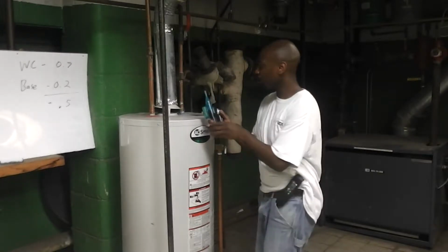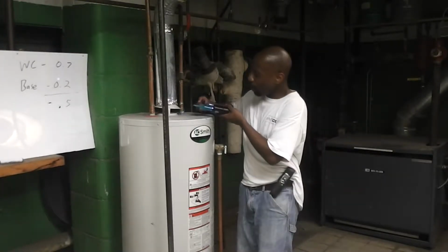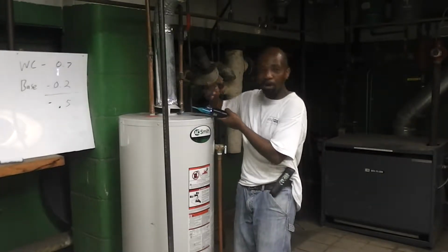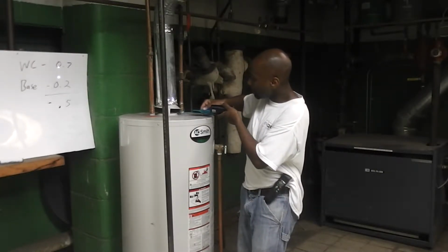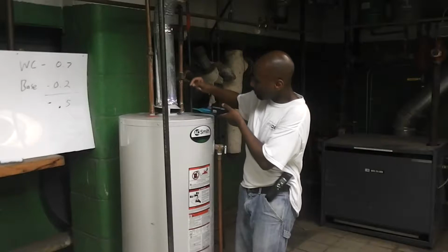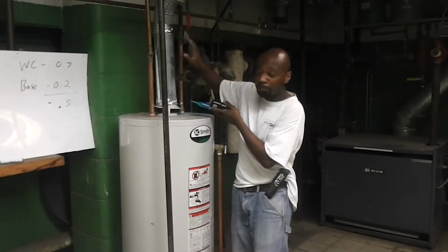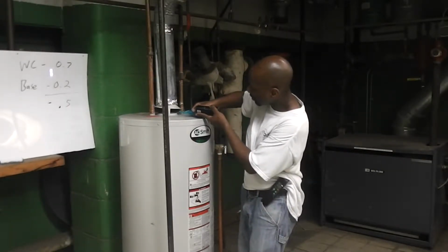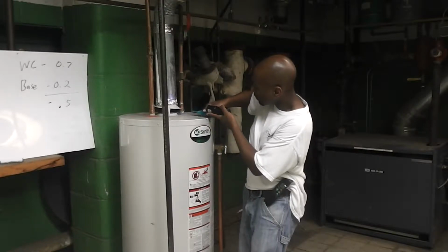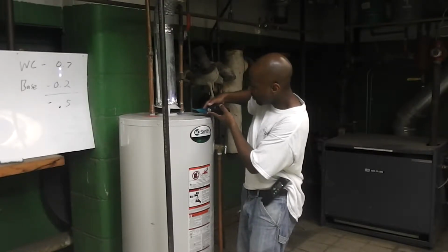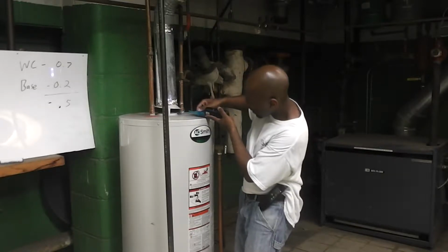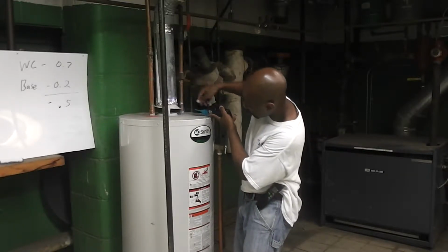We're still okay. I'm going to use a smoke stick. I want to see if those gases are actually coming out. Remember, the time is 60 seconds I'm looking for. So as I'm doing this, I want to see if the smoke is actually being drafted up the flue pipe. I'm still counting seconds in my head. I'm approaching about a minute. So far, it looks alright. It looks like those gases are still going up.